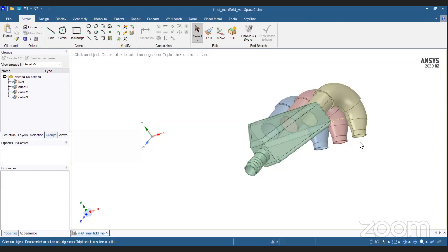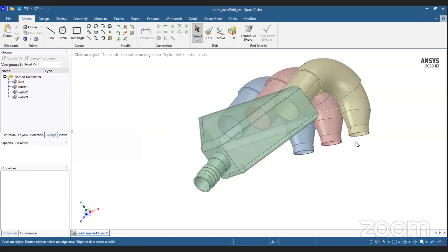So Snigdha, if I had a water basin with an open top, that wouldn't be considered watertight, correct? Because the fluid's being replaced with air, for example. So even in that case, if you were to do an open channel flow problem, you would have to create a bounding box to cover it up. So basically, you have to create a closed domain, no matter the flow being external or internal. Awesome. Thanks. So yeah, in this case, like I said, this geometry is far from clean.